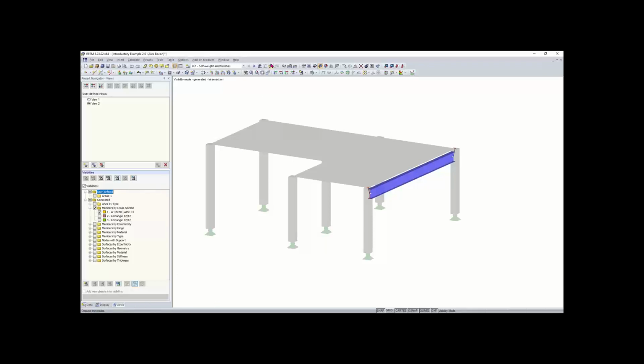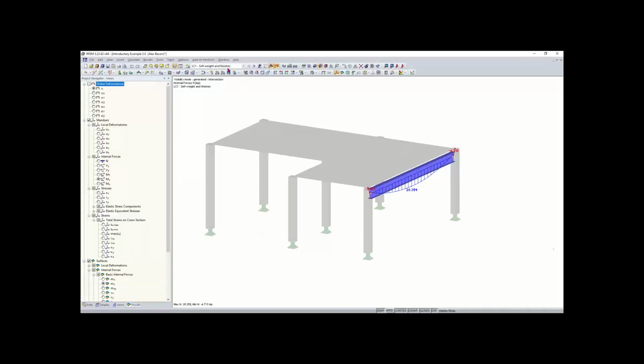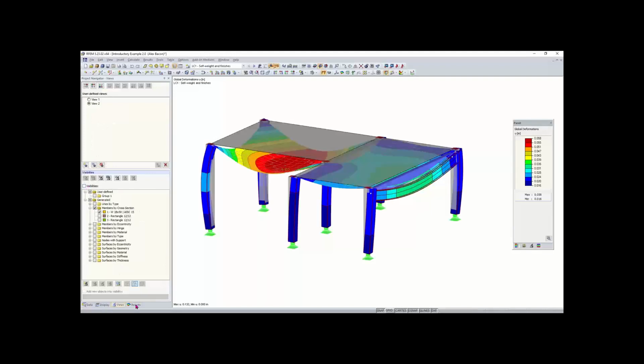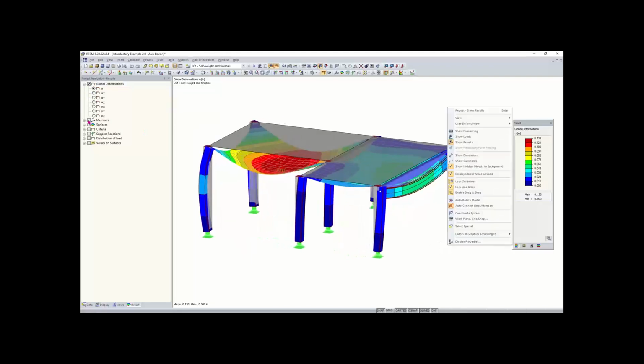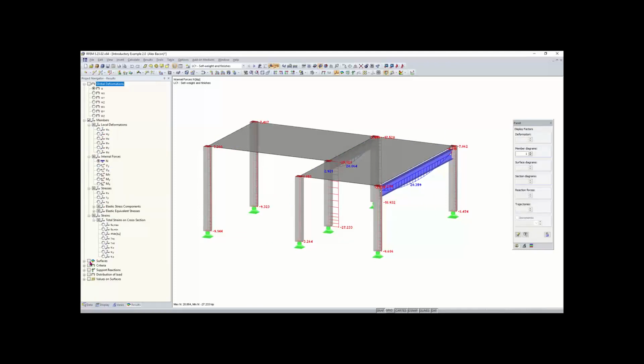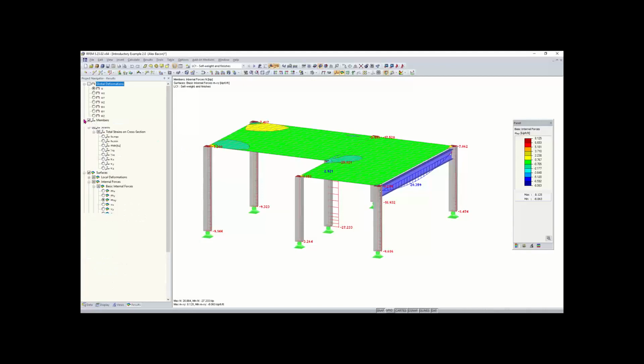The third tab we would have is our results tab. So if I just run the results for this model quickly, then we will see our results tab, and that will pop up at the bottom here, only if we have results ran. So I just ran my load combination 1, and if I turn off my visibilities, and then now you can see in my results tab, this is again similar to the other menus where we have our expanding and collapsing folders. So right now I have global deformations checked off, and we're viewing our resultant deformations. And you can see we get a nice look at that. And then we can also check out our member basic internal forces, as well as our basic internal forces for our surfaces as well, if we would like. But we'll go over more of this in detail later, so don't feel too rushed to learn this real quick. We will be going over all of this in the training. But just want to give a basic overview.